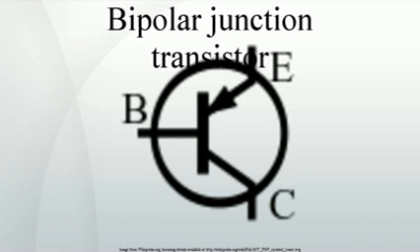There is a lesser chance for recombination within the smaller base region, and the charge gradient is increased across the base, and consequently, the current of minority carriers injected across the emitter junction increases. Both factors increase the collector or output current of the transistor in response to an increase in the collector-base voltage. In the forward active region, the Early effect modifies the collector current and the forward common emitter current gain is given by the following, where V_CE is the collector-emitter voltage, V_A is the Early voltage, 15 V to 150 V, beta_F0 is the forward common emitter current gain when V_CE equals 0 V, r_o is the output impedance, I_C is the collector current.